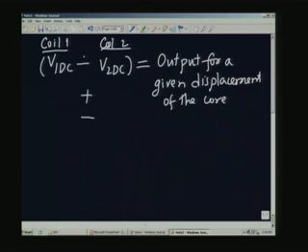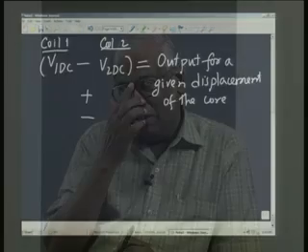So, this voltage will change sign, and if you remember what I showed in the figure earlier, you had a linear variation for both positive as well as negative displacement of the core, and this follows a linear relationship as was indicated there. This voltage is proportional to the pressure difference, and the pressure difference has given rise to a certain displacement which is a linear relationship.